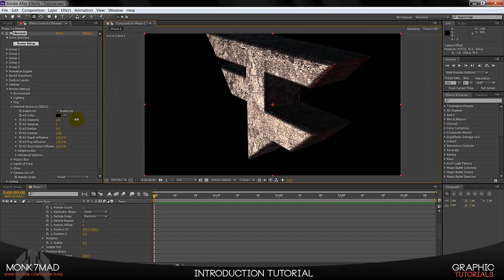Don't know, but we've got the intensity. You can very gently, if you look right in the angle point here, you can just about make out the intensity of it, and you can also change the radius. This would also make it more obvious. So if I remember rightly, I think my favorite settings for it were an intensity of about 4 and a radius of 0.8.